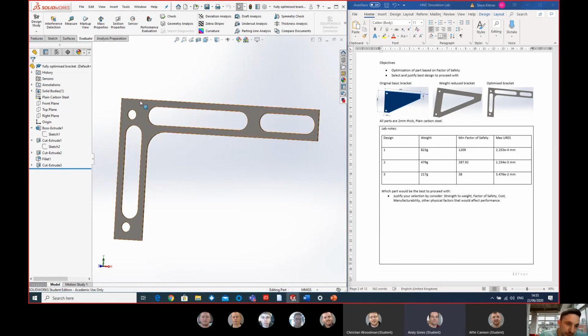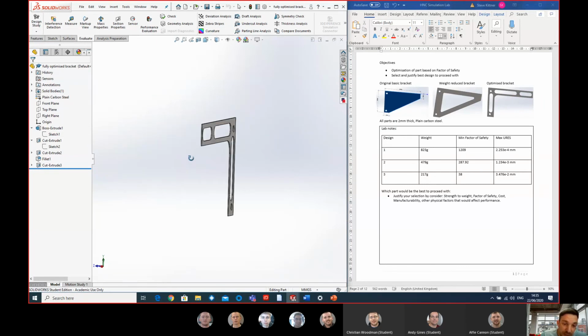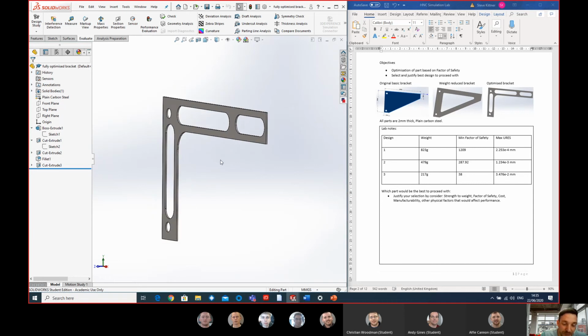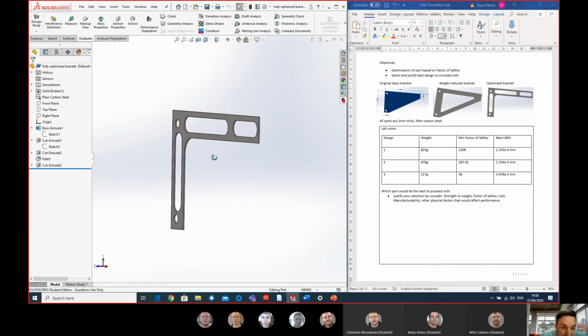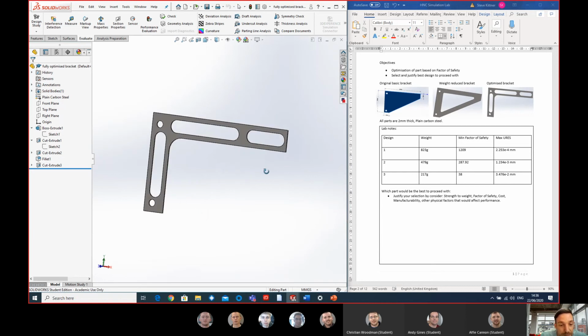What if you put a radius up in this top corner, because most of those simulations didn't show much stress up here? So that radius would sit a little bit closer in here, and you'd get a bit better sheet utilization again. So that's kind of what this wants to inform you of. There's some basic data you can take from it, but ultimately it can help empower where your design goes. So would I design that bracket ultimately out of 2 mil thick sheet of steel to hold a 1 ton pressure? Probably not, because of the buckling that I think would go on.